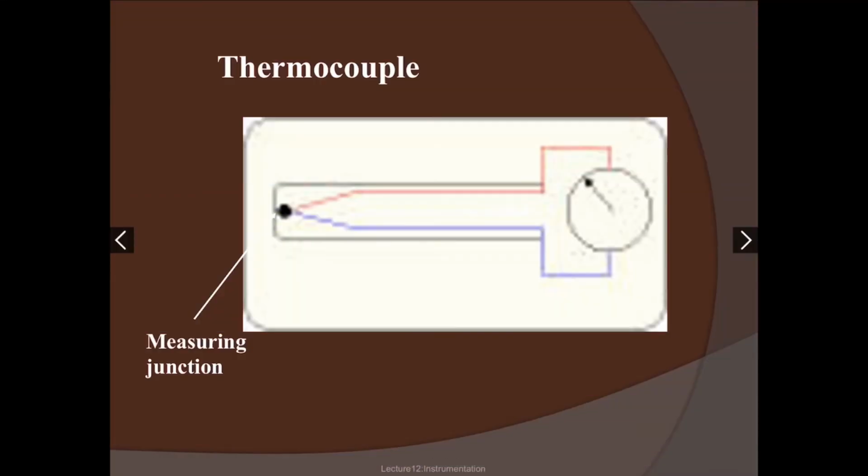Using the thermoelectric effect, both Peltier and Seebeck effect, the temperature sensor is designed. Thermocouple is a temperature sensor that outputs voltage. Thermocouple consists of two metals that are connected together. A voltage is developed, which is a function of temperature at the junction. The voltage is generated by a thermal phenomenon called Seebeck effect.